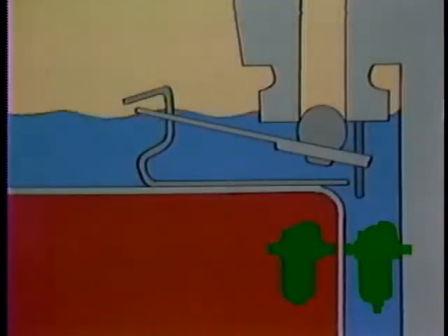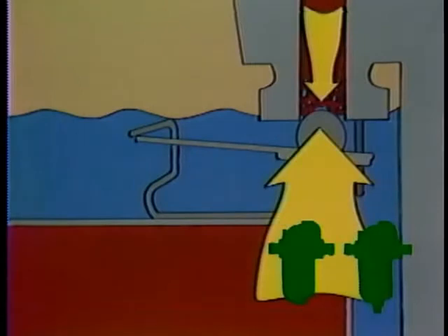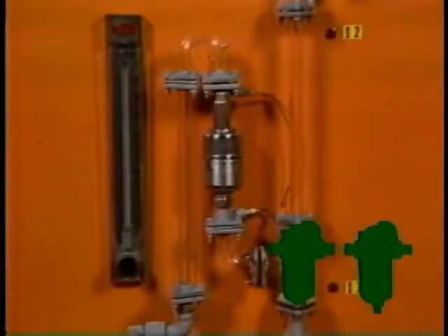Whenever the valve cracks open, condensate flashes across the valve seat. Because of the volume and velocity increases that accompany this flashing, there is a sudden pressure drop in the orifice throat, resulting in an increase in differential pressure across the valve. If the entering condensate flow doesn't provide a sufficient water level under the bucket to counteract these increased closing forces, the valve snaps shut. F&T and bellows steam traps have modulating outputs at very low loads. In these traps, the opening and closing forces tend to balance out as the load decreases and the trap doesn't fully open or close, but modulates with the condensate flow.